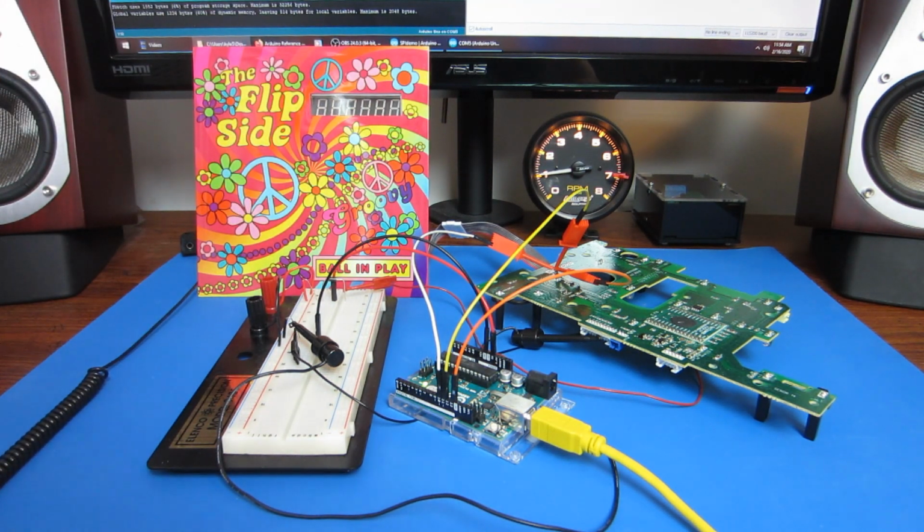Even though the microcontroller on the playfield is running at 3.3 volts, I'm hoping that the 5-volt Arduino will still be able to see the SPI communications. It's got a threshold voltage where any voltage above a certain value is considered a binary 1. And I'm hoping that even though the 3.3 volt microcontroller is not putting out a 5-volt value for logic high, the 3.3 volts it's putting out is above the Arduino's threshold for what it considers to be a logic high. So we should be able to see the 1s and 0s that are coming out of the SPI bus.